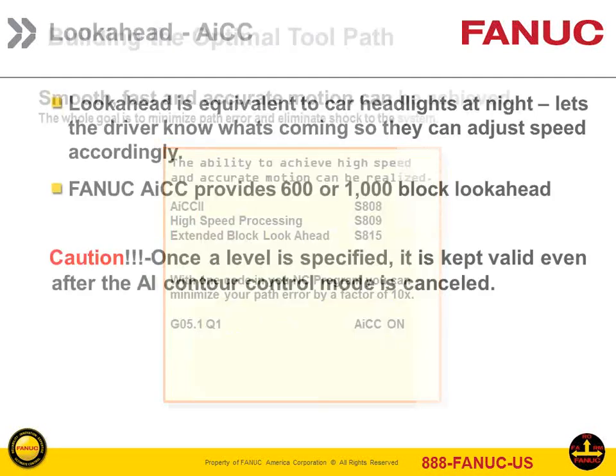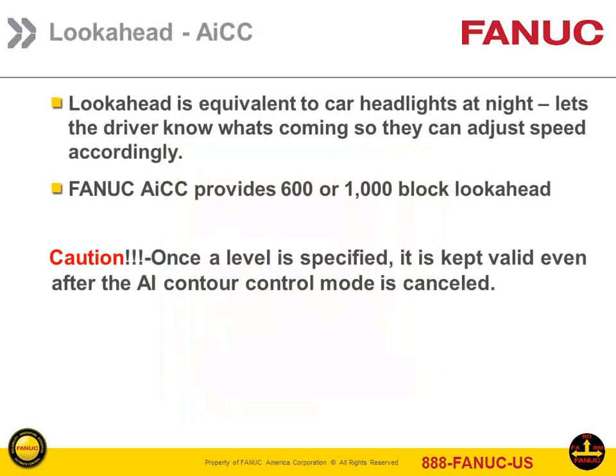Okay. And then, talking about look ahead, and again, FANUC loves to use the driver analogy. Look ahead is equivalent to having car headlights turned on, so the driver can see what's coming up ahead, so he can allow for it. That's what look ahead will do. And with FANUC, you can get up to 1,000 block look ahead.